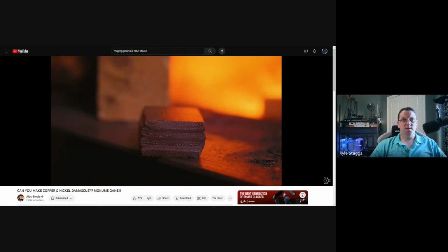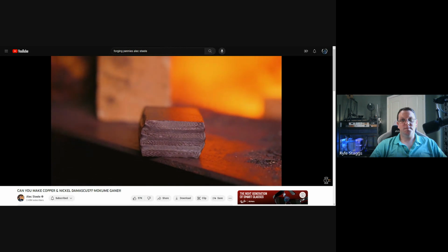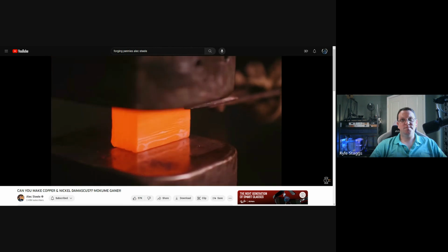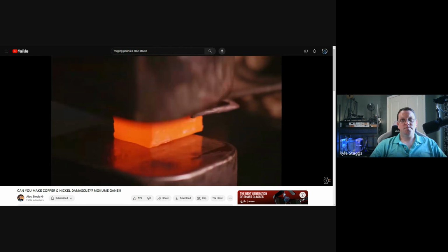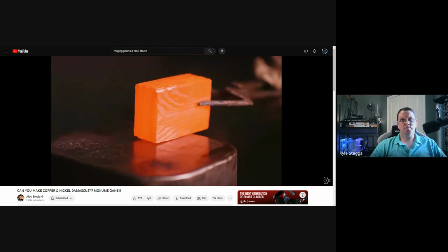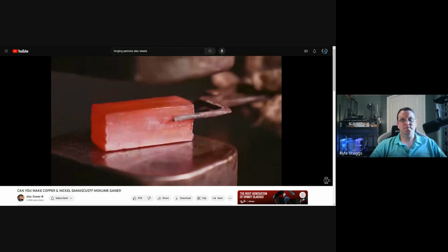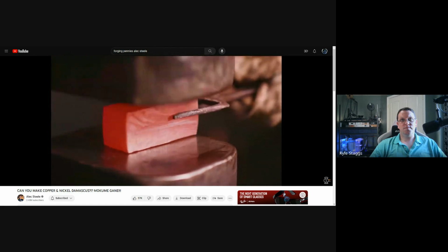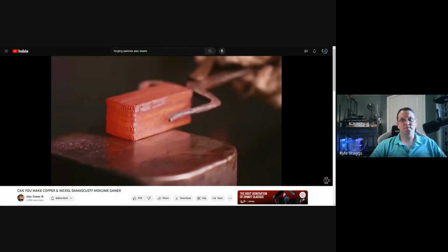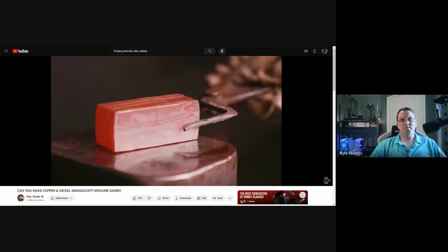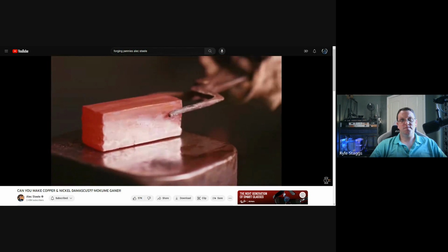Check it out! I think it's fused! I was terrified. I was concerned that it only fused because we had copper the first time, but I really think it's done it. I think it's together, and look at how beautiful that pattern looks. I think I found that the key is to work a little bit on each side. It's not to work a lot from one side, but just take a few blows and then turn it. A few blows and turn it.